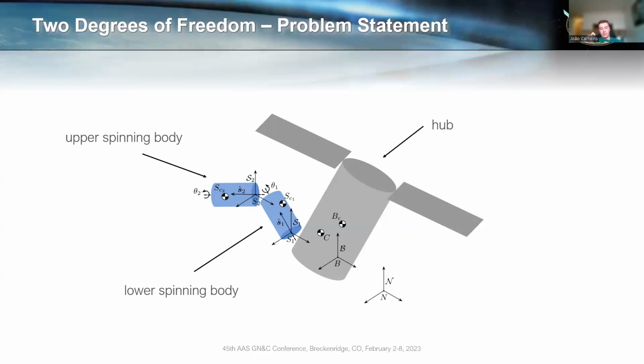Now, this is important because when you're controlling this 2-axis system, it is sometimes very useful to lock one of the axes as you control the other body, then lock the body that you've already controlled and control the other body. That way you don't have to account for the gyroscopics, and you don't have to account for this cross-coupling that happens when both axes are free to rotate.